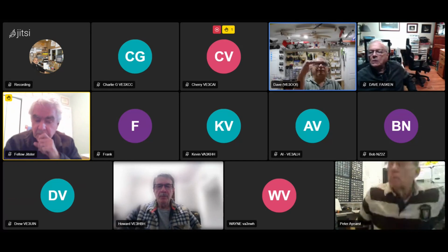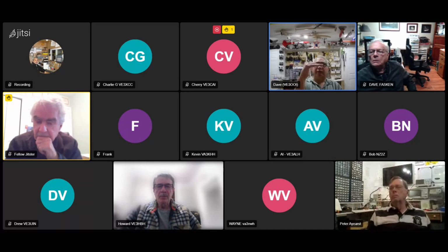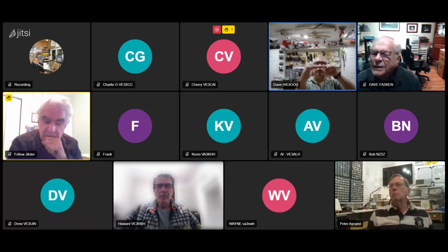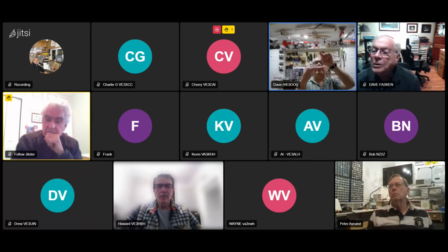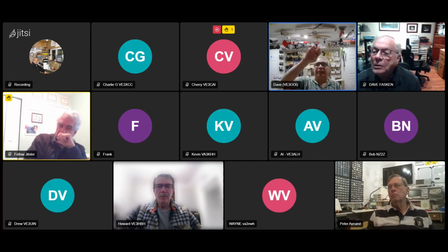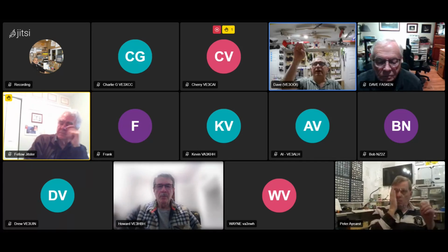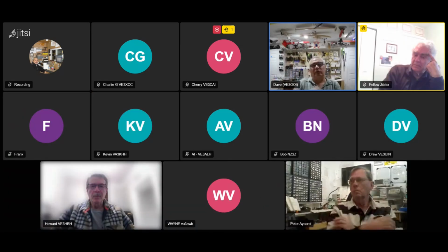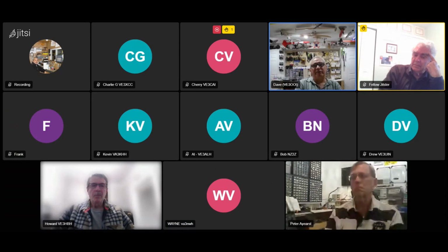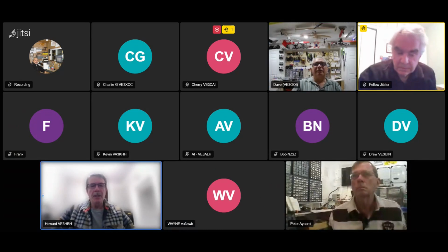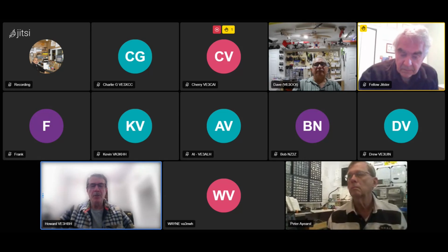If it's biased exactly in the middle, and you put in a signal that's really big, it's going to take it up to the point where it bends over the knee, it's going to clip, and it's going to generate distortion and harmonics. Does that make sense? That makes sense. I wasn't thinking of the differences between the DC and the AC, but that makes sense.